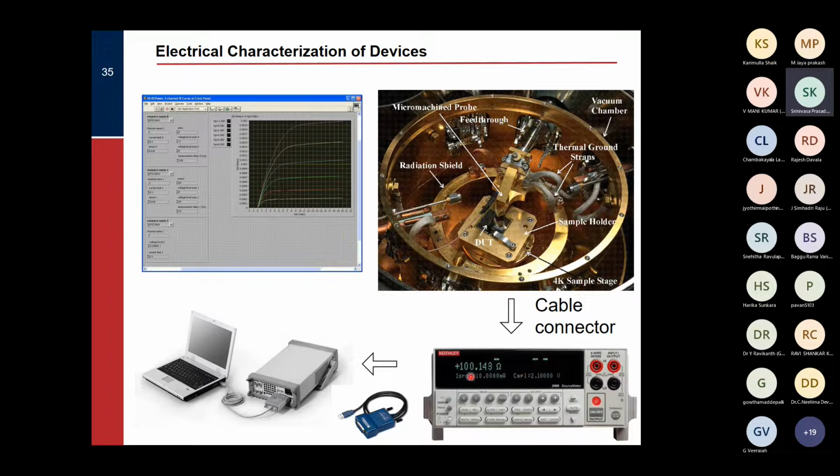So you connect it. Now, since these are programmable, you don't need to physically change the voltage or current here. You can actually control it through a computer. So here you use some sort of GPIB, or let's say some interface bus cable. And you can see this back end will be connected to a computer screen. And here you need some program like LabVIEW or something similar, which will communicate between the computer and the instrument, and that instrument will perform the measurement and collect the data.